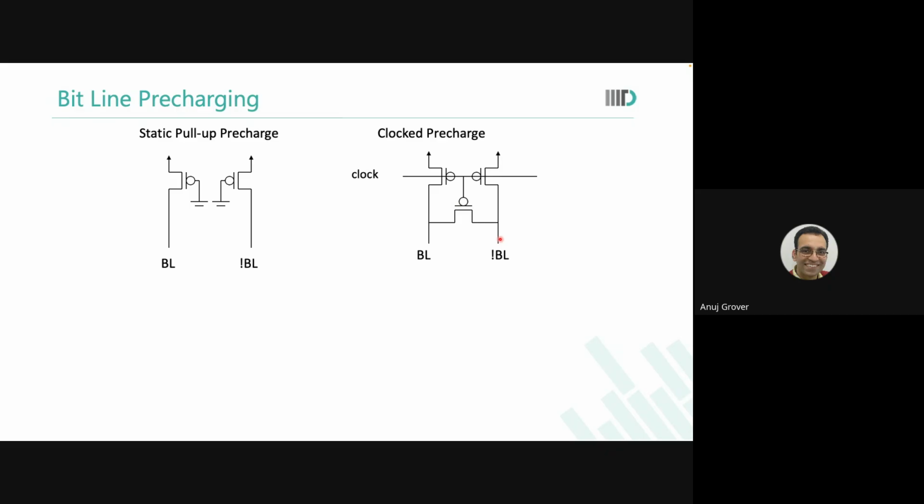At a system level, that means that, okay, after the memory, there is still some margin I have before the next clock will come, and I can put some combinational logic there. But if the access time gets delayed, anyways, the cycle time will also get delayed. But I have lesser margin to put combinational logic at the end of my memory. Is that okay? Does that help you? Any more questions?